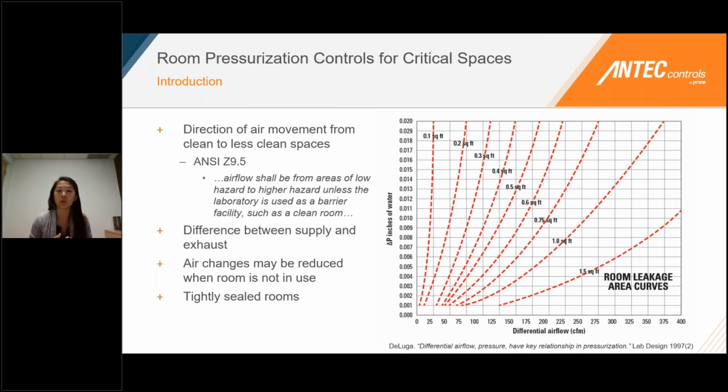Now, when we're talking about clean room applications, these are typically positively pressurized spaces. In this case, the experiments or the procedures done in the space itself do need some sort of protection from any contaminants entering the space. Clean rooms will still typically have a fume hood of some sort. That fume hood will be exhausting air itself, but the entire lab space will be positively pressurized so that there aren't any small particles or contaminants that affect what's happening in that lab space.